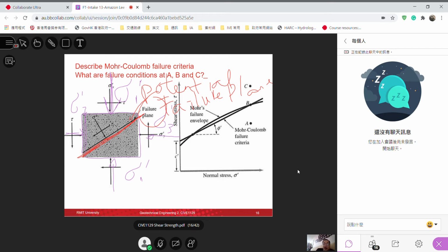In geotechnical engineering, what we are finding is something that potentially happens. As I mentioned before, the actual failure occurs in the microstructure: the soil grains fail across this microstructure and join together into a continuous failure plane. So it's not truly a straight line.